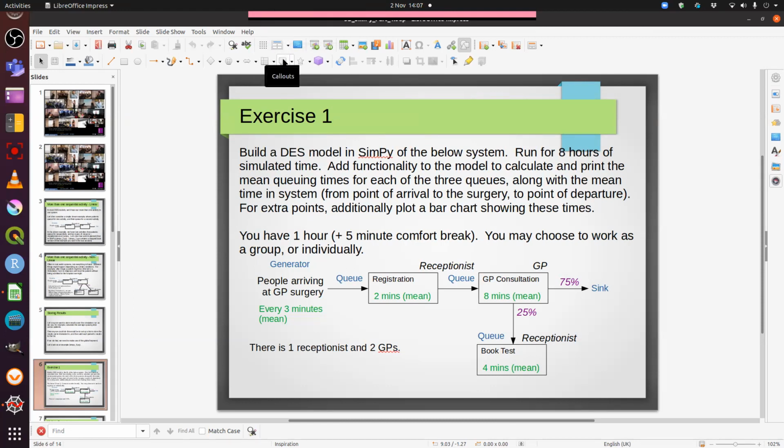So the short answer is no. What you tend to want to do is minimize the variability that you're seeing. You want to get to a point at which your system is stable and generating stable results. So you're doing enough runs that you're not getting huge diversity in the results coming out. Obviously, the more runs you do, the more the results will homogenize. One easy way to do that is just to use a stupidly high number of runs, and then you'll always hit that. That might be practical for simple models, but for more complex models, that's not really practical. So what you can do is monitor the spread of your results with different numbers of simulation runs, and that will give you an idea about the number of runs you need in order to get the right kind of results.